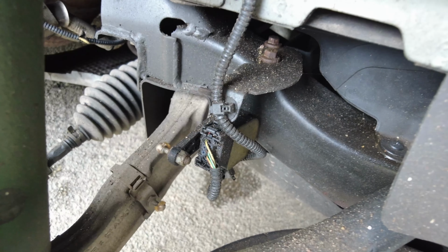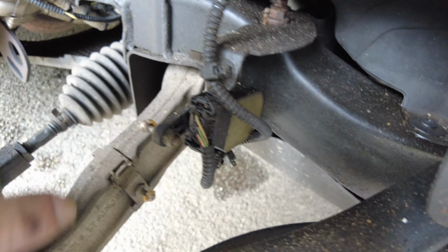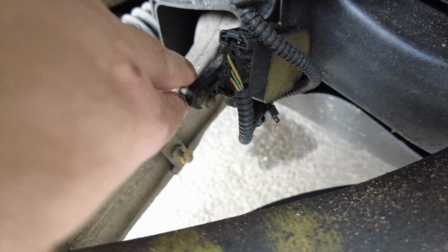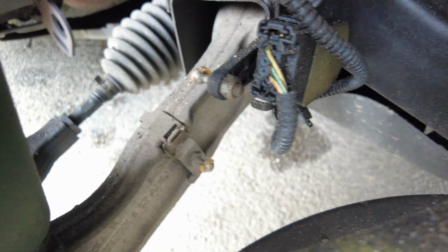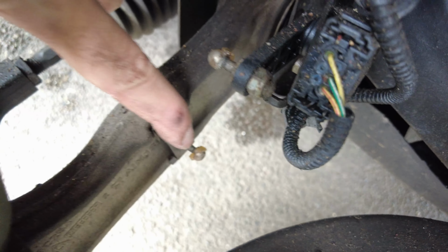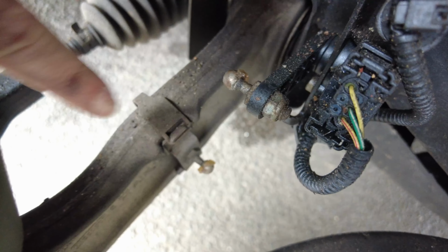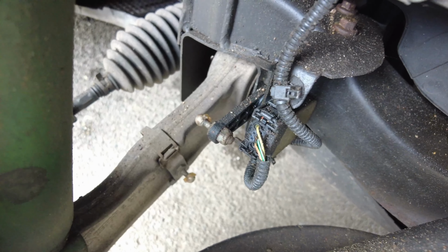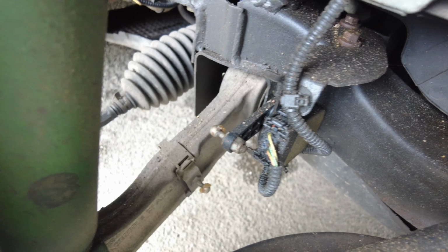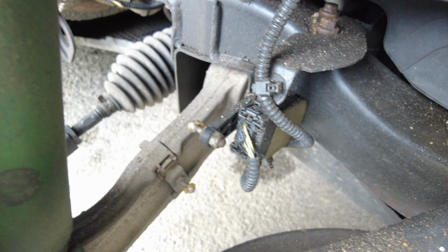Okay, so I've taken the wheel off, and immediately I can see what the problem is with the front axle sensor and why it's frozen. The reason it's frozen is because the linkage between the front axle sensor and the suspension arm just down there has gone. It's just simply not there. I can see the remains of the ball joint end there and just here, but there is nothing linking the two.